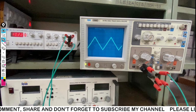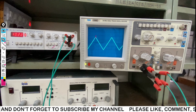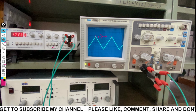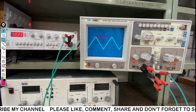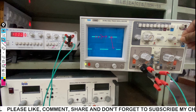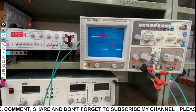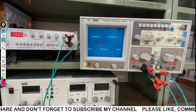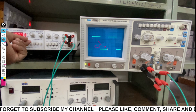If I change the function to triangular, then for triangular as well the wavelength is the same, 2 point something divisions. Then time per division multiplied by it gives T, and then f is equal to 1 upon T, and the same for the voltage divisions. Same in the case of a square wave: we have to start from this part and end on this part for the calculation of the wavelength. Then we can calculate the time base frequency and then the voltage per division in the vertical direction.